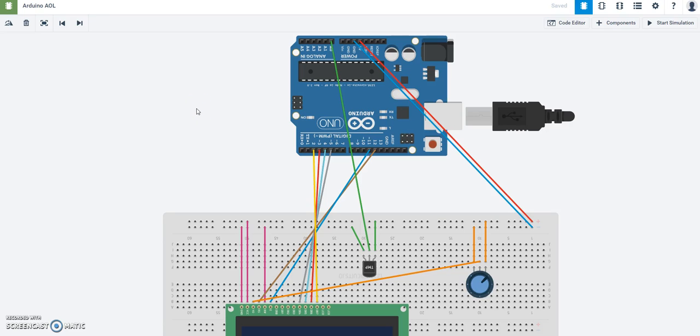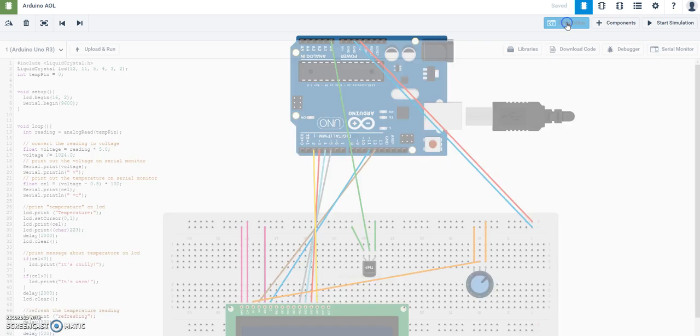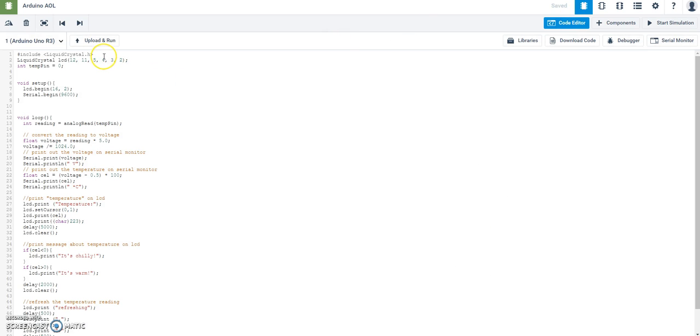Once the Arduino setup is complete, you can move on to coding the Arduino. So the first thing that must be declared is the code library being used, which is LiquidCrystal. It's LiquidCrystal because LCD actually stands for liquid crystal display, and that's why you must use this code library. After that, you can declare that LiquidCrystal is LCD.